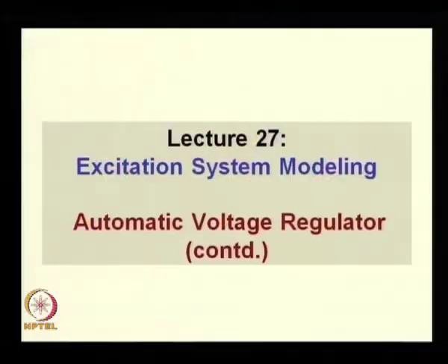So, if you open the manual of a synchronous machine in real life, you will find that the nature of the AVR etc. is expressed not in terms of state space equations or differential equations, but in terms of block diagrams. So, we have to interpret the state space relationships or the mathematical functions in terms of what is given to you in a block diagram. Okay. So, today we will continue that. Today's lecture is a continuation of our discussion of the automatic voltage regulation. We are really looking at a few transfer function blocks.